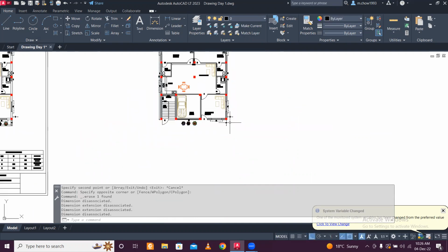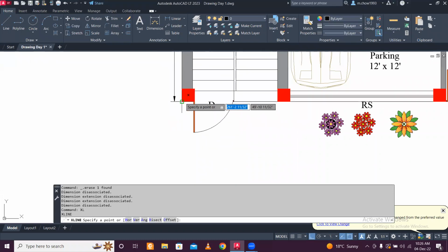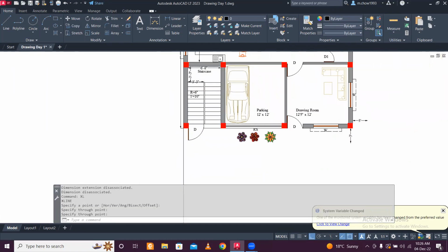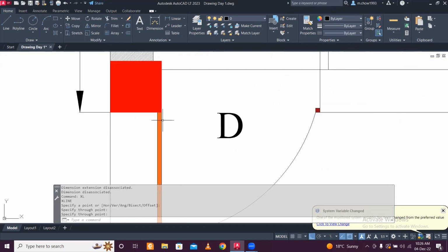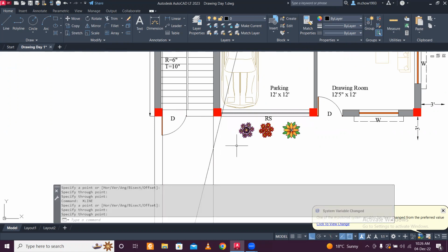The plan is here. So we'll draw the elevation. So you use the command XL enter to just make the lines here. So first of all, we'll go for the elevation. So XL enter, and then you can use the space button always effectively to make these lines. If any error, you can press Ctrl plus C. Okay.